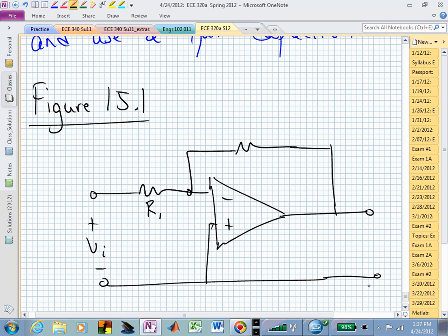but we know that's not going to be sufficient, right? Because what would that give us? That's going to be an inverter, so we need to do something that's a little frequency dependent, and if we put a capacitor in parallel with that resistor, we'll have a better success rate at designing a low-pass filter.